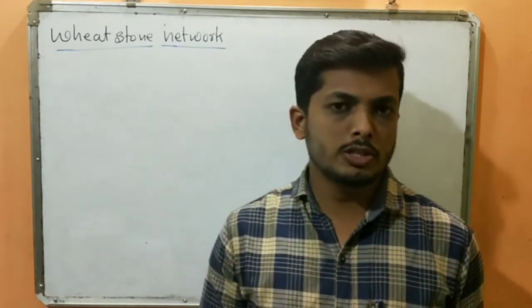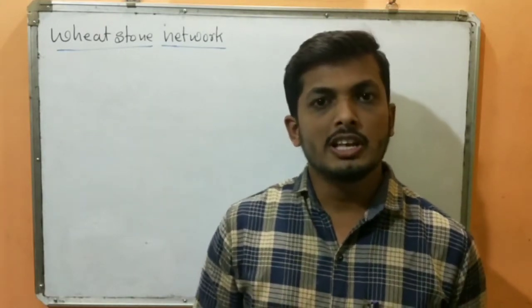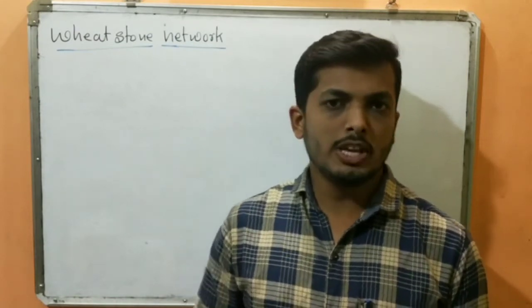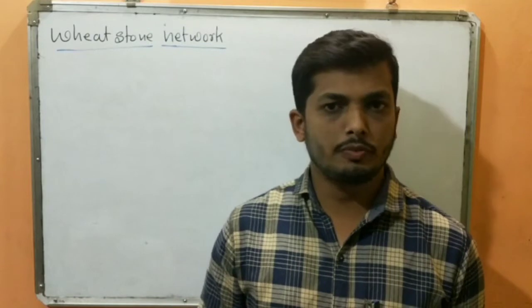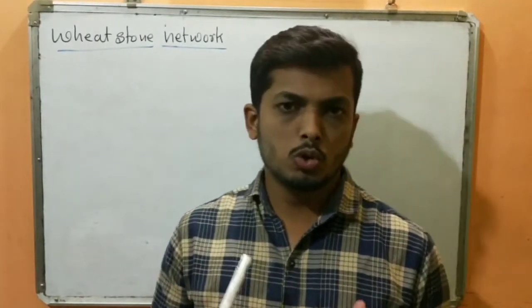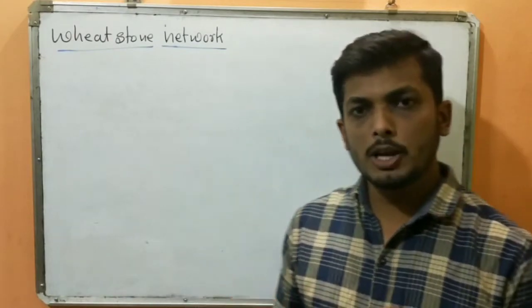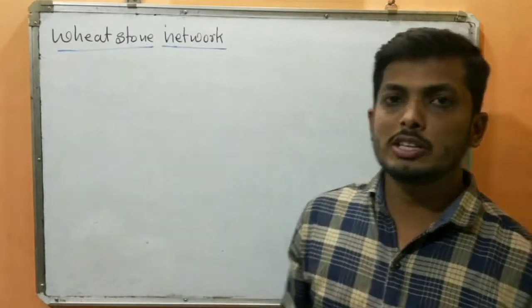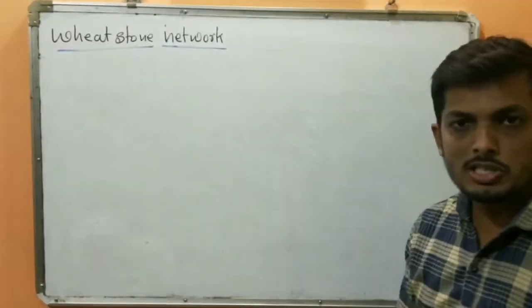And one more law, which is Kirchhoff's voltage law. It states that the algebraic sum of the IR products is equal to the algebraic sum of the EMF present in the various branches of the circuit. Okay, so Wheatstone network is totally based on those two laws, and we are going to apply those laws in a Wheatstone network.